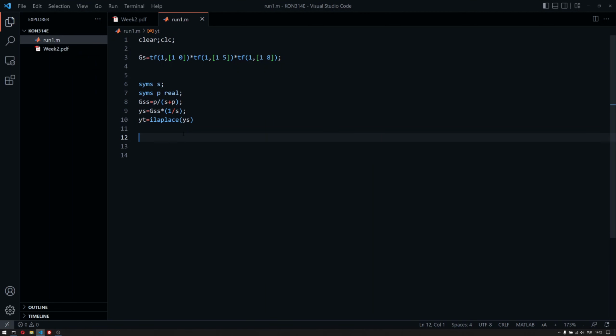So we know that this system, a first order system, should always have a real root, because it has just one root. It cannot be complex. We're dealing with real coefficients in terms of polynomials. Therefore, the root should be real. And we also know that, therefore, there will be no overshoot.